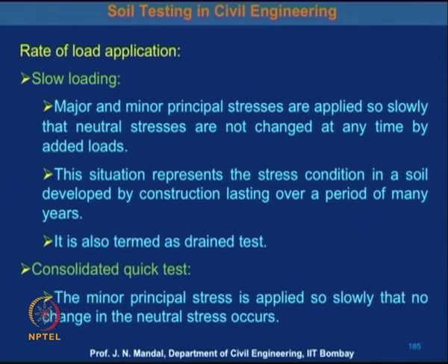Now, what is the rate of load application? There may be a slow test or there may be a quick test. If it is slow loading, that is, major and minor principal stresses are applied so slowly that neutral stresses are not changed at any time by the added loads.